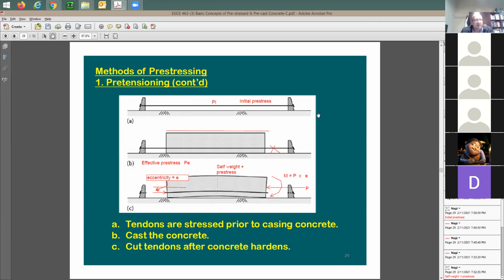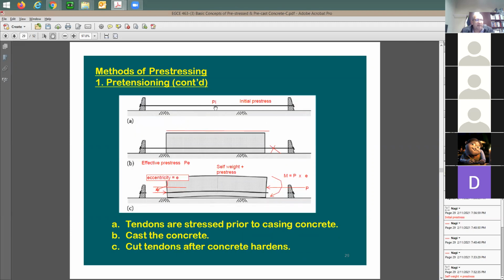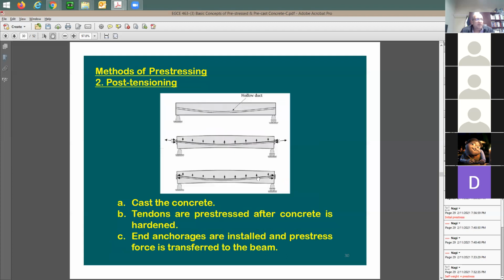Exactly. So if you like to do it this way, you need to come here and push down at this, right? You need to put something here to hold it down at the floor, and this can just take the floor and fly in the air. It can just do big damage. So this is cheaper. So when you do a design like this, you need to take care of this in your calculations. At the end, you're gonna see that the pre-stress force is in the mid-height of this section.